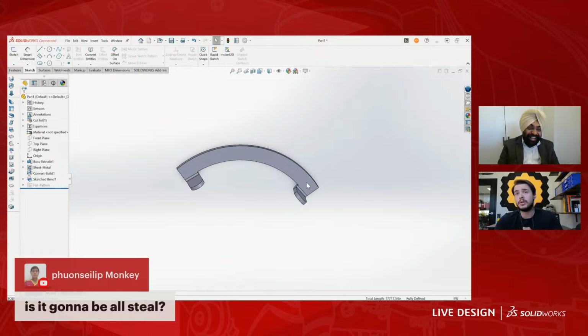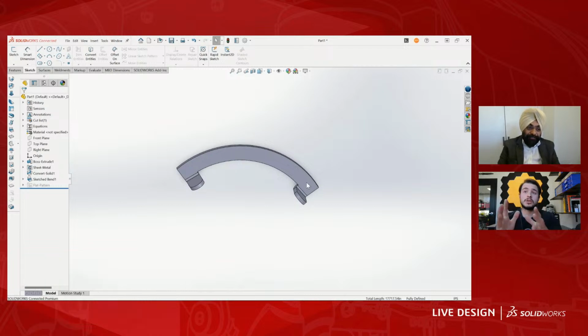Most of the section is actually going to be aluminum. Since not every single joint is going to be powered, we do want to reduce mass. Because if you're swinging this whole arm around, and even if the arm is supported by the weight of the legs, it's still a lot of mass to get accelerating and a lot of mass to slow down, and you don't want it to tip your entire body.